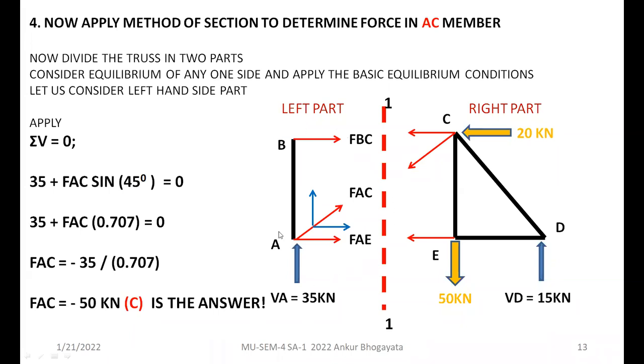Since we have done this the first time, it took more than 8-9 minutes to explain to you. But once you practice it, it won't take more than 5 minutes to determine the forces in the desired members. Right. So with this, we have calculated our first answer within no time. As you can see how wonderful it is, and it is very simple also. We have just divided the truss, replaced the members by forces, simplified the inclined forces into components, and then started using sigma V, sigma H, sigma M.